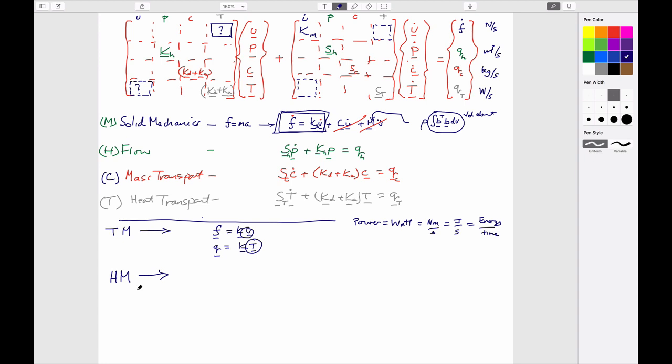If you hold it in a plastic bag and, for instance, put this inside a container that doesn't allow it to expand, then instead of being very compressible and compressing, if you constrict it in a sheath that doesn't allow it to expand, it'd actually be very stiff because all the fluid that is trapped in there is trying to get out. It can't get out quickly enough because it's constrained, and therefore you're measuring really the compressibility of water, which is basically the same compressibility or stiffness as rocks. You know, compressibility of water is about a couple of gigapascals, and rocks are maybe 10 or 20 gigapascals in terms of their stiffness.